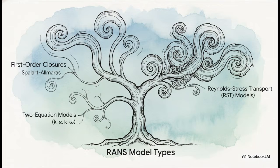So these models are basically grouped by how many extra equations they solve to describe the turbulence. The simpler ones use a concept called eddy viscosity, which is a fancy way of saying they treat the effect of turbulence as if it just makes the fluid a little bit stickier. The more complex models, though, go a step further and try to directly solve for the specific stresses and strains caused by the turbulence, giving you a much more detailed picture.